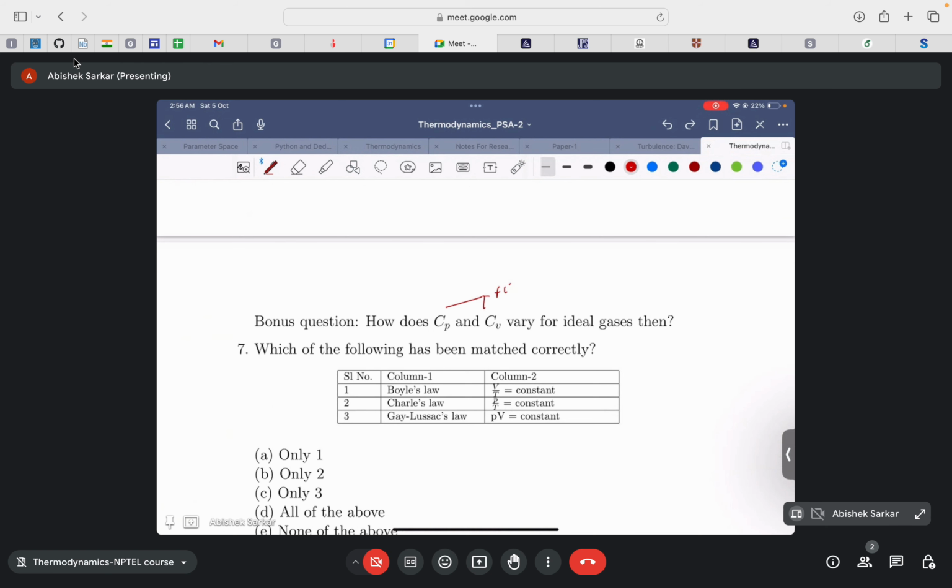But there are many instances in numerical questions where, even while dealing with an ideal gas, they ask you to take the specific heats as some constant value, though ideally they should be functions of temperature in the case of an ideal gas. To simplify the calculations, they usually ask you to take the specific heats as constant. But don't consider it a generalized case, because in general they should be a function of temperature even in the case of an ideal gas.